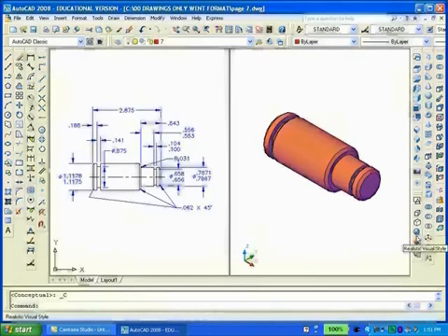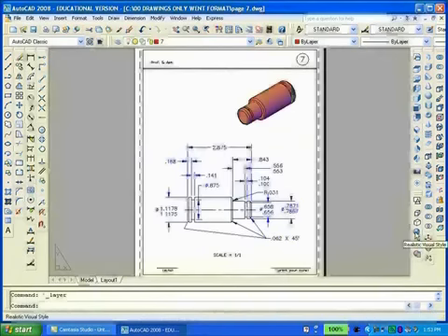The object is rendered and the solid is finished, so I'll click on the Layout button and set up the desired viewports in paperspace. I'll freeze the viewports layer, and the detailed drawing is ready for plotting.